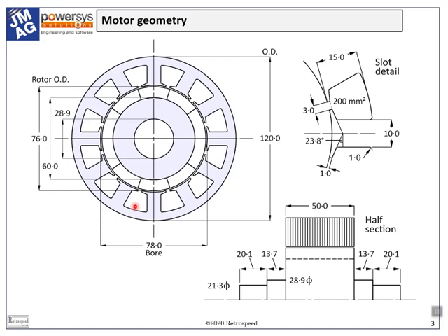We're not inventing anything new, but the example brings out a number of fundamental electrical principles which can be used in a more general context. The second part is the choice of wire size, the number of turns, the number of parallel paths in the winding. From this we can calculate the resistance, the inductance, and the generated EMF. And once we have this data, we will be able to calculate the torque and the power.